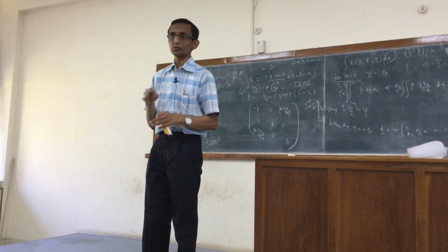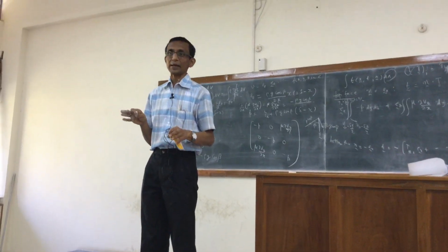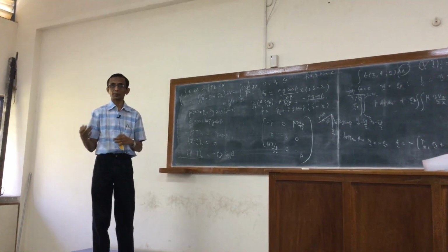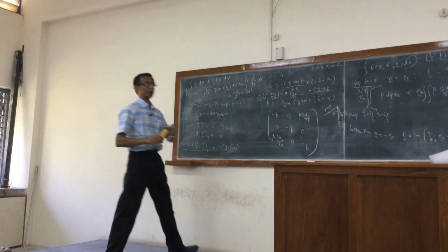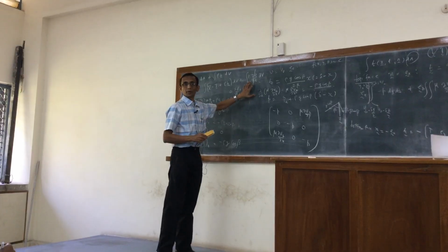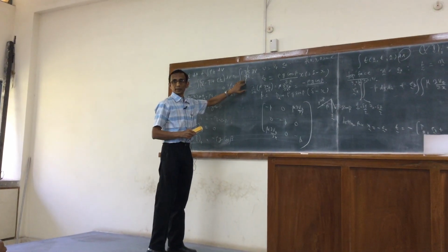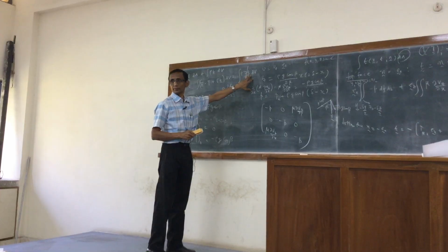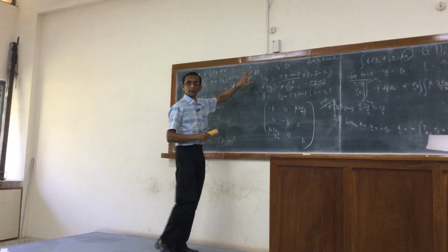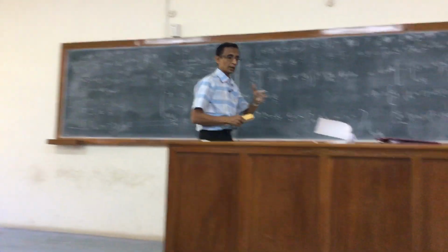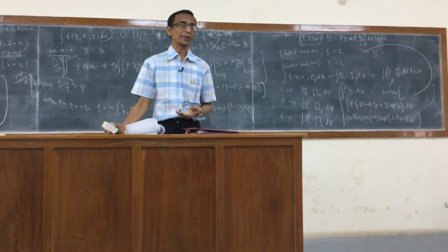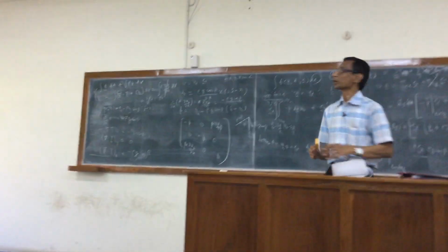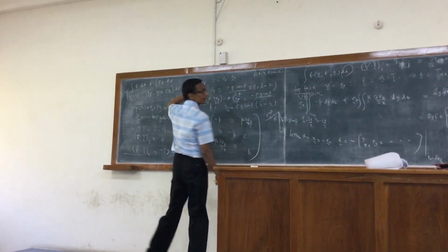The inertial terms we have shown identically vanish, because if two of the velocity components are zero, the variation of vz along z is zero. So that will give rise to this. So if I wanted the total force, I could have simply gone directly to this and concluded that the net force acting on the volume element would actually be zero from the equation of motion, by simply looking at the left-hand side of the equation.